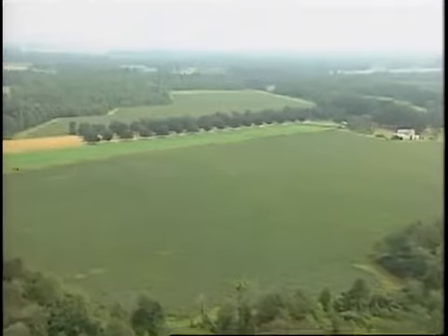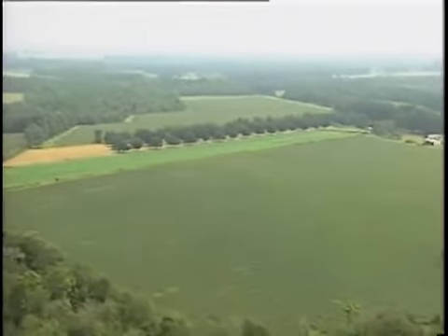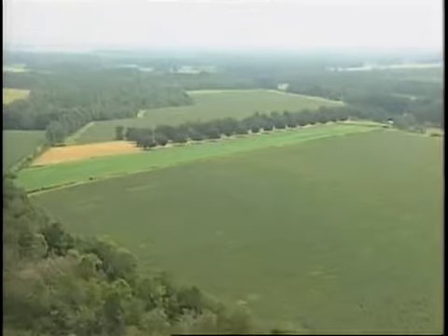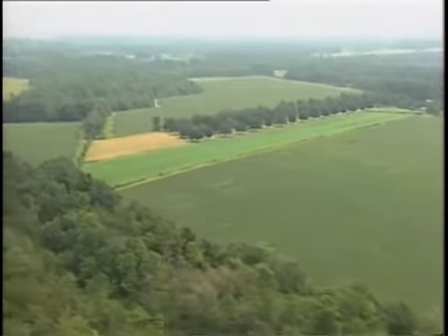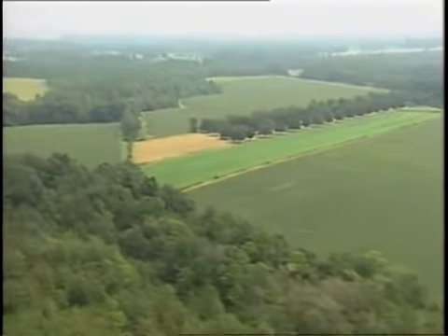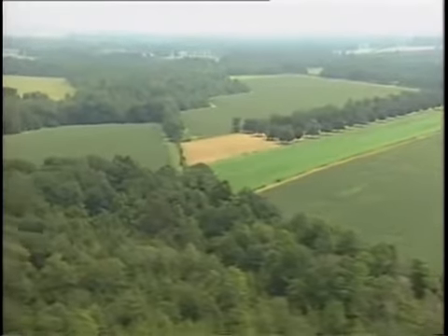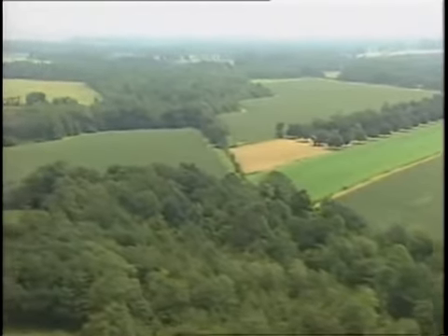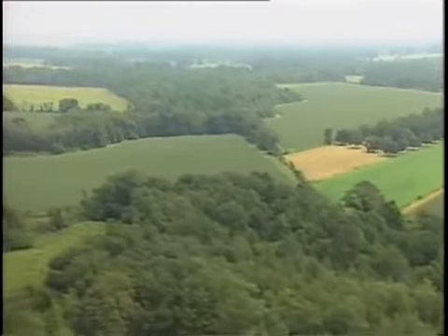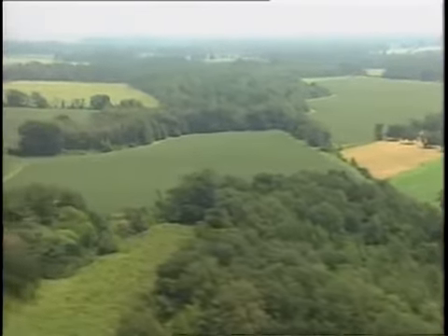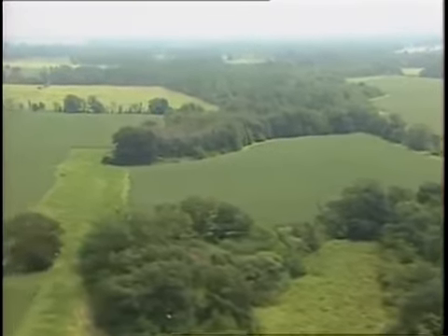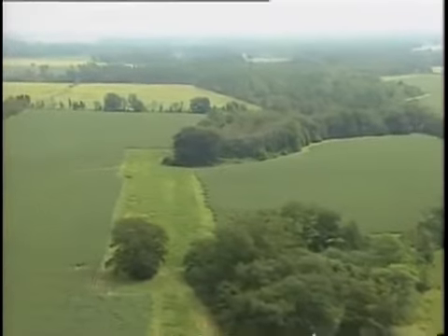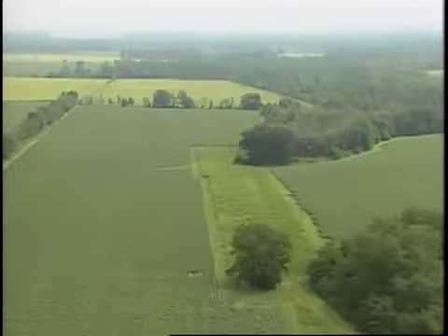After takeoff, the pilot locates the field to be sprayed. Prior to treating the field, the pilot visually checks for obstacles including towers, wind turbines, power lines, poles, trees, irrigation equipment, fences, variations in the terrain, nearby houses, and sensitive areas such as surface water and wildlife habitat. In some cases, a trained ground observer will ensure that field conditions are safe for a pilot before the aircraft is sent to a field.